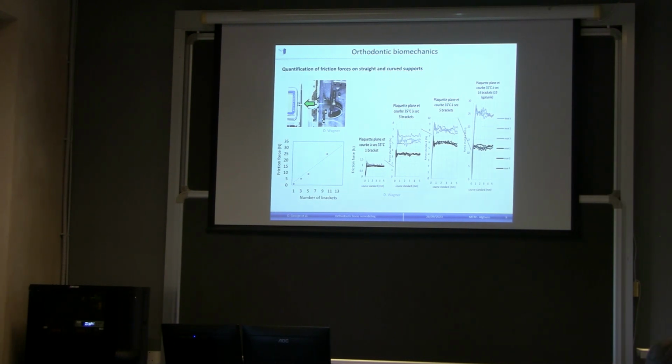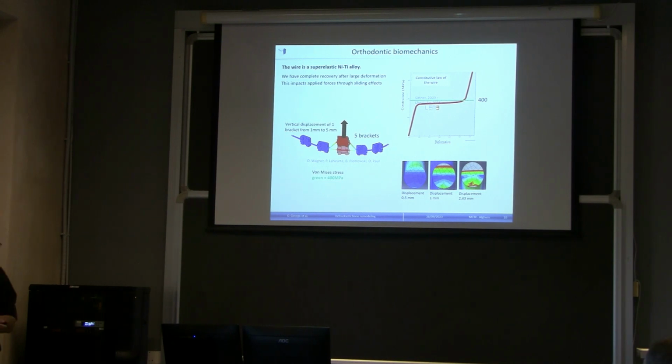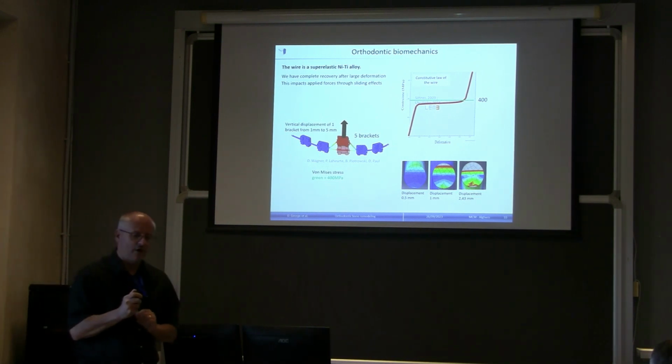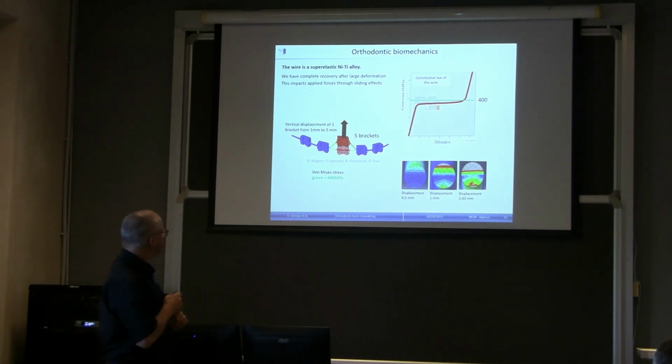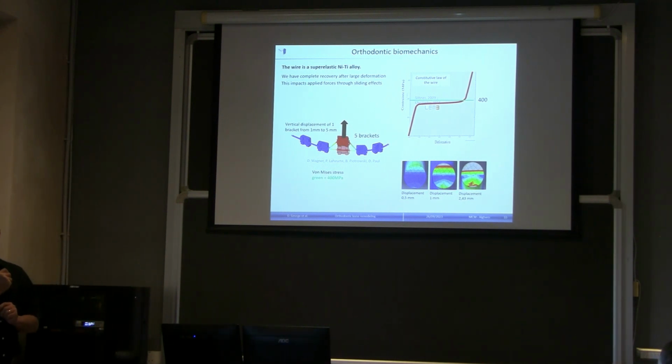There is another parameter which is also important, which is the deformation of the wire. In this study we worked on nickel titanium alloys, which are superelastic. You see here the constitutive law of this material, and the yield stress of this material is roughly 400 megapascals.